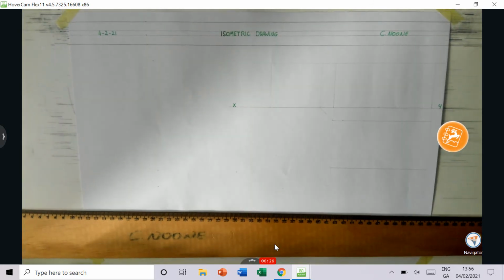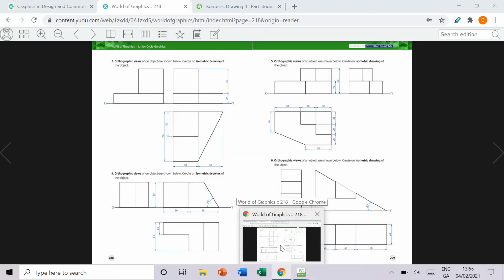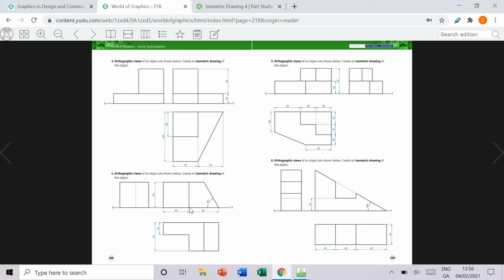Okay, so we have shapes now that they're going to fit into. It's just a matter of finding these firm lines here now. So I'm going to start with the elevation. We see that we have a 50 mm line here, and we're going to have a vertical line up. Then we have to go across 58, and that's a line up at 60 degrees.